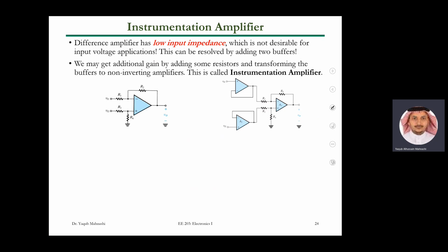When we say the load has no effect on the voltage, that is right; in other words, it has a very large input resistance. Okay? Always when you do isolation, you want to isolate the input from the source, you want to use a buffer. And this is the same way.